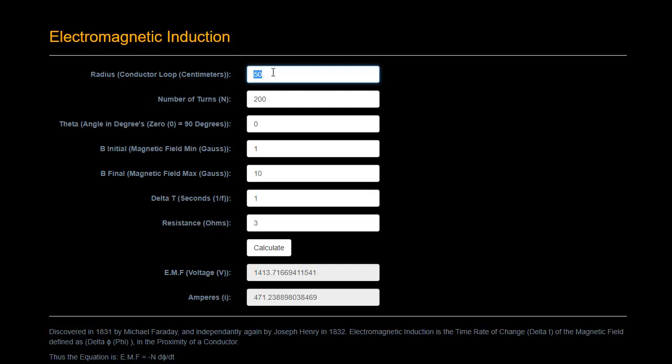I mean, I don't have 10,000 turns. I might have a couple of hundred or so turns. I think from memory, I suggested starting off at 40. 40 is a pretty reasonable number as well. But again, this is a little bit of a juggling act. You've got to think, these two partnered output coils each see themselves as the primary and secondary. So our partnered output coils are both primary and secondary for each other.